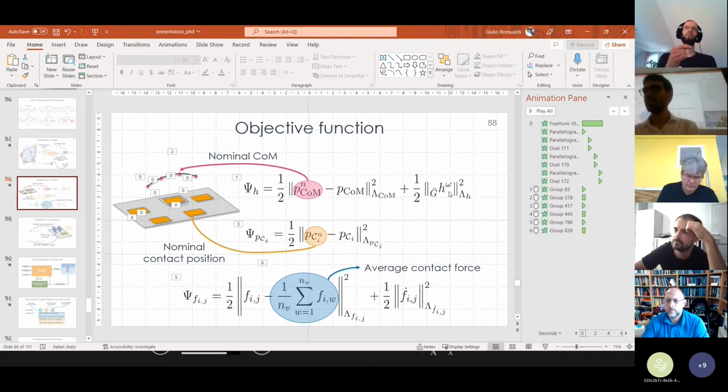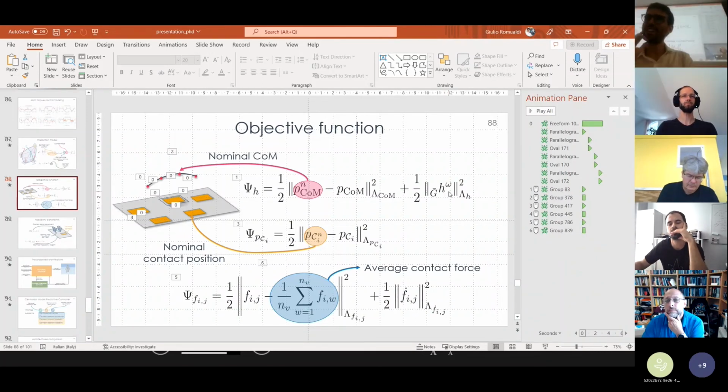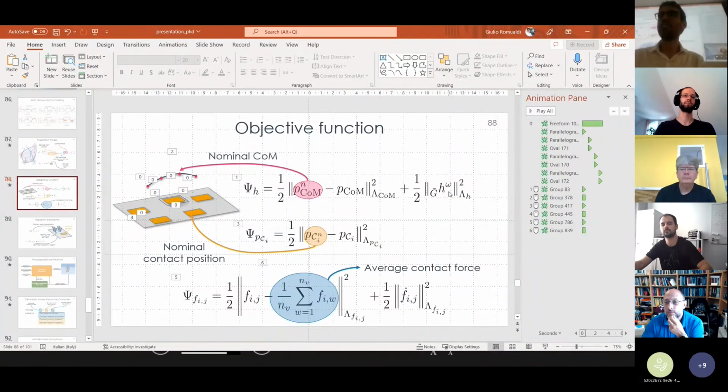What I'm also pointing at is, when you push the robot, let's say hard, having a reference equal to 0 would not be the right solution here, because it tries to keep the angular momentum equal to 0, and so it will move the arms a lot in order to counteract the error. Also, it may be possible that when you walk at high velocity, having an angular momentum equal to 0 may generate strange motion on the robot. Okay.